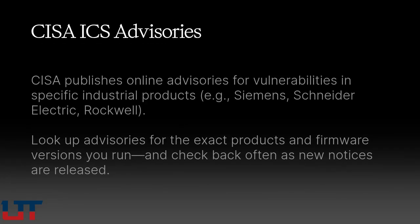CISA, or the Cybersecurity and Infrastructure Security Agency, publishes Industrial Control System Advisories online. These advisories cover well-known vulnerabilities in specific industrial products: Siemens PLCs, Schneider Electric equipment, Rockwell Automation systems, and others. If you operate any ICS product, check whether CISA has issued an advisory for your specific product and firmware version. New advisories are published frequently.